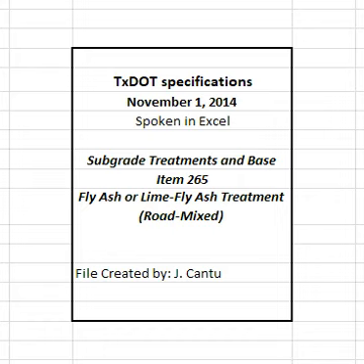4.6 Finishing. Complete finishing operations within 2 hours after final compaction. Immediately after completing compaction of the final course, clip, skin, or tight blade the surface with a maintainer or subgrade trimmer to a depth of approximately 1/4 inch. Remove loosened material and dispose of it at an approved location.